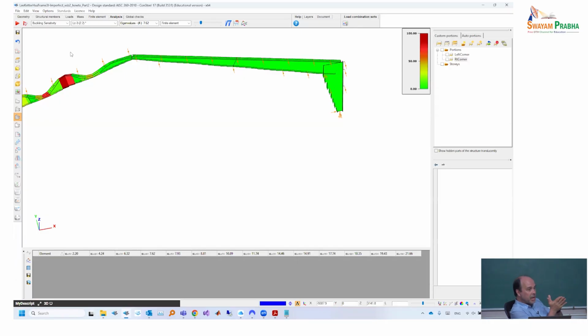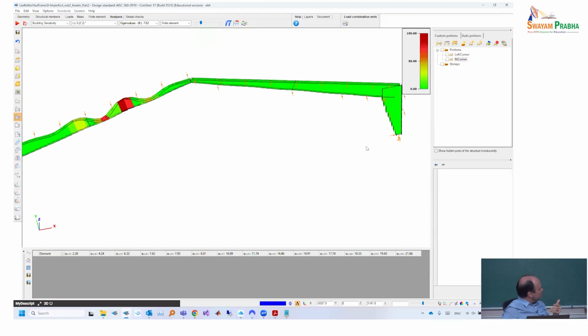At the moment, the lower value we have set in Consteel is 10%. So that means that we will assign the element with the 100% and all the other elements which are producing at least 10% from this mode. So in that case, it may mean that we add also another element, but certainly definitely not the column, for example, which is 0. Okay, so it really works very nicely for those which are definitely separated modes. So it's very nicely separating the well-separated modes.